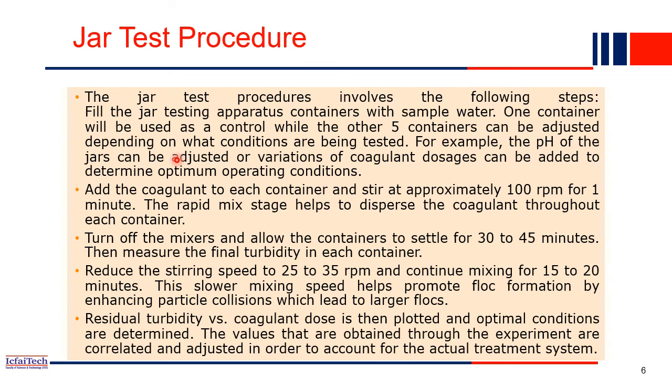After you start the experiment you will see that even after you add more coagulant, the deposition of the suspended particles will be the same. It is not increasing. So you can take that as the optimal value, and that dosage will be applied in the actual water treatment plant.